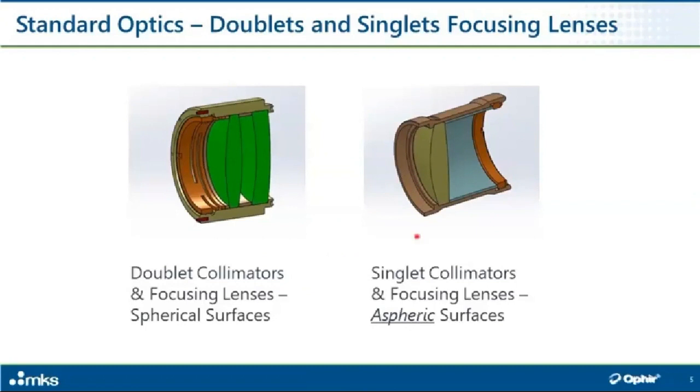The advantage of using an aspheric surface is that firstly you use only one lens, and consequently the absorption is decreased by half. Now, absorption is one of the most important parameters in laser optics. Because of the high powers of the laser, even a small amount of energy absorbed by the optics can cause damage or degraded cutting quality.